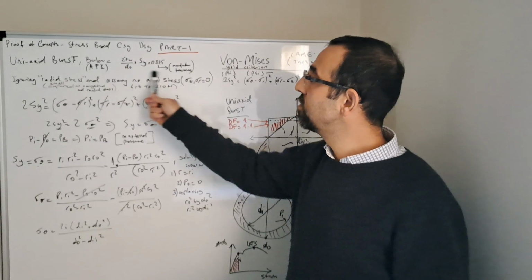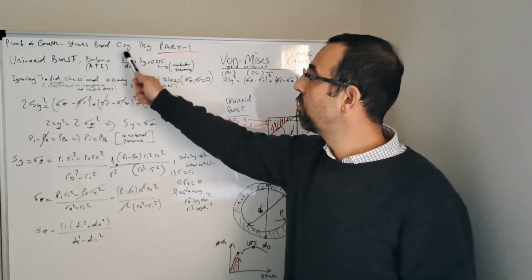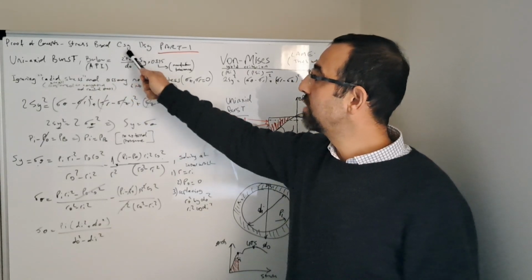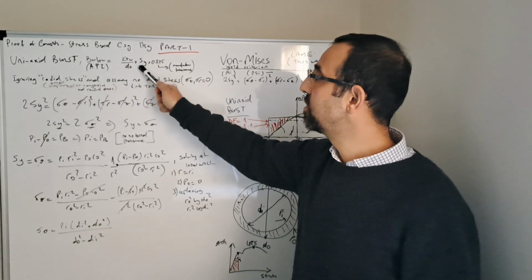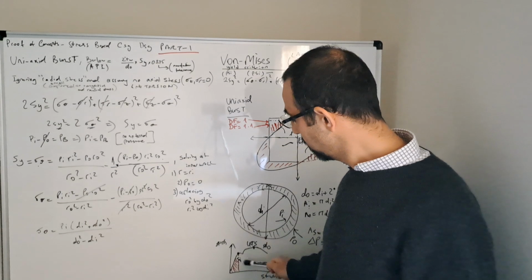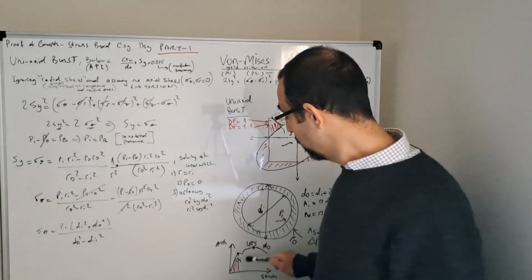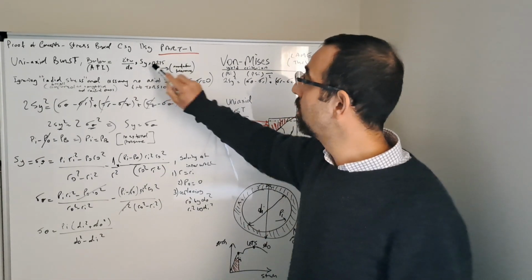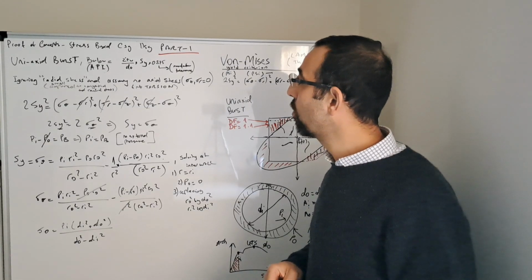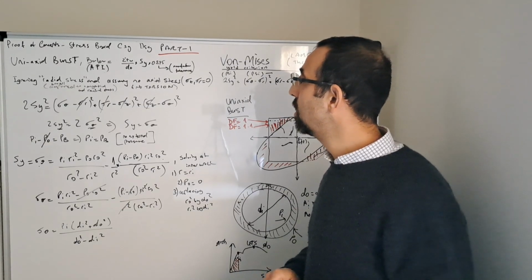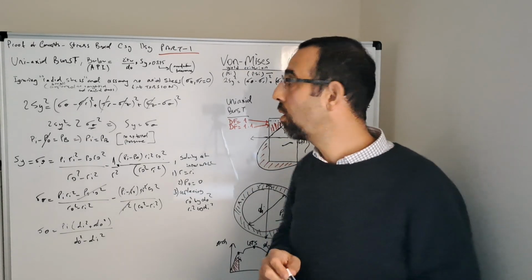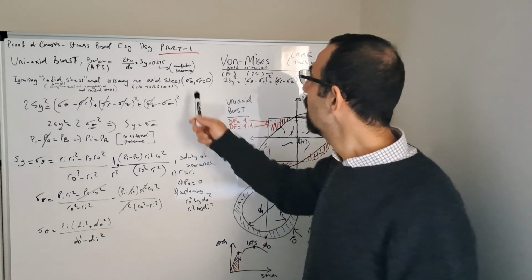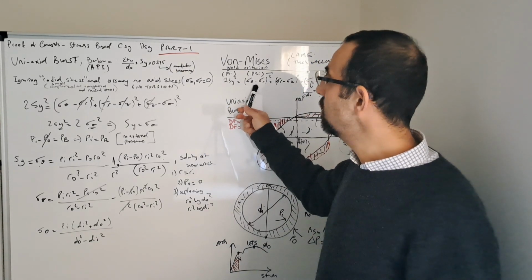So the equation, as you know, is 2 times the wall thickness. That's the nominal wall thickness, by the way, and then divided by the outer diameter times the yield strength. Yield strength is this minimum specified yield strength, not the tensile strength. And then we basically correct it with a correction factor to reflect the 12.5% API tolerance on the wall thickness. So we will still use this equation.